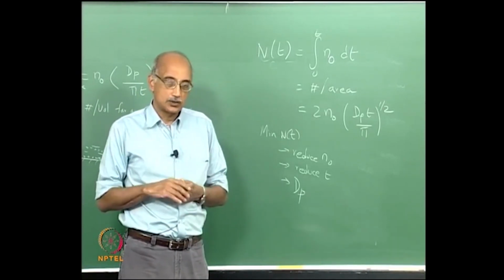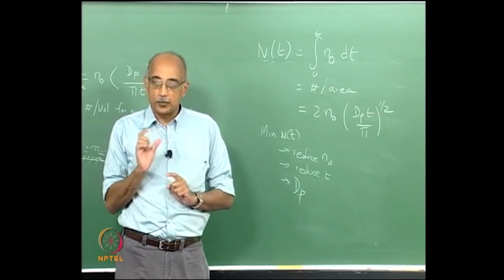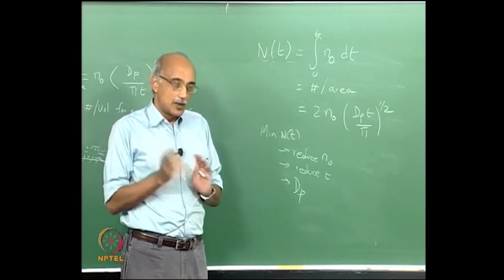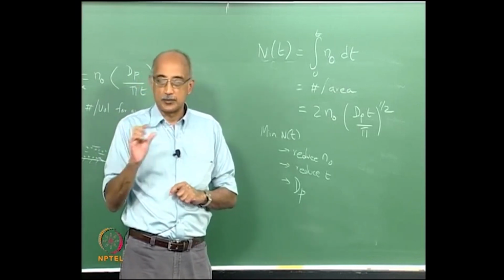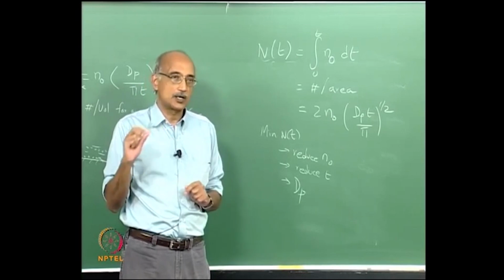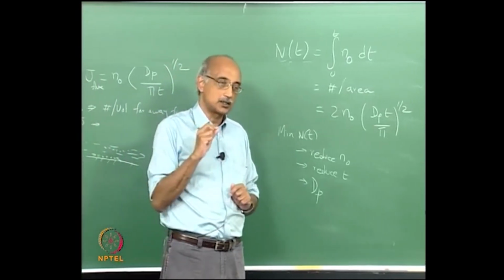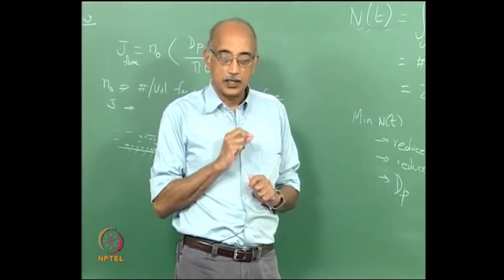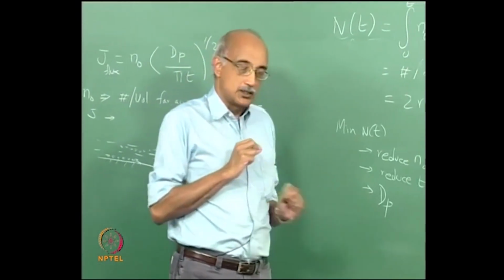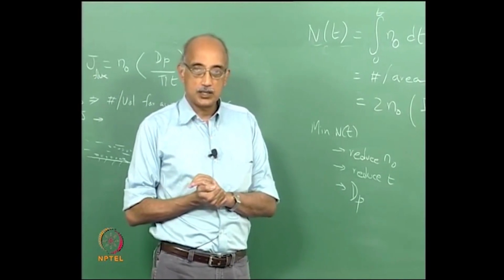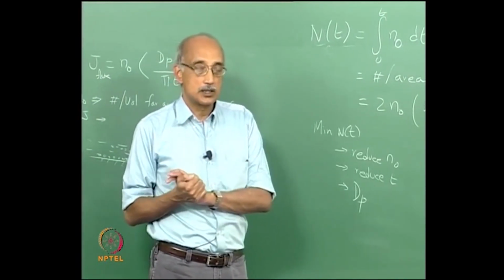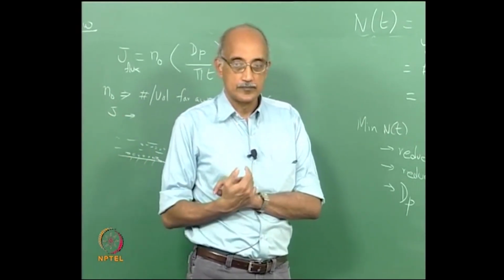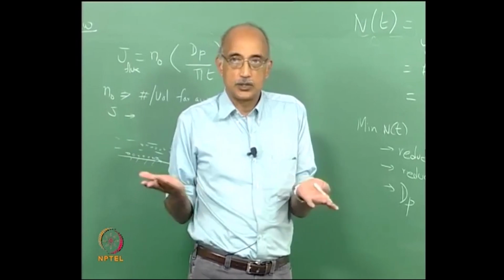So actually it turns out there is an optimum size range of particles which will minimize the overall deposition. That optimum size range though varies from application to application. It also depends on product sensitivities. If you have a product that is very, very sensitive, let's say to submicron particles, then this is a good strategy to minimize diffusion, because even though that might increase the mass flux of larger particles by the other transport mechanisms, they don't affect your product, so you don't care.